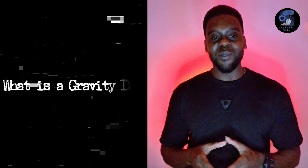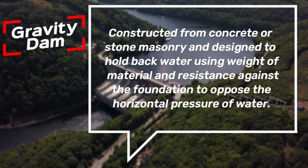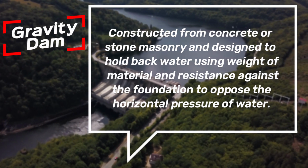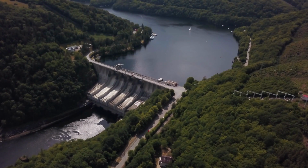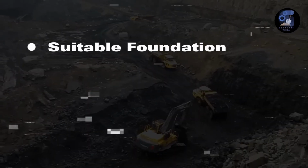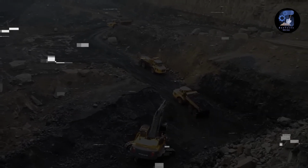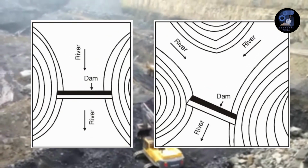So, what is a gravity dam? A gravity dam is a dam constructed from concrete or stone masonry and designed to hold back water by using only the weight of the material and its resistance against the foundation to oppose the horizontal pressure of water pushing against it. Of course, the ideal and most economical site location should have a suitable foundation for the dam, and the width of the river at the dam site should be minimum so as to keep the length of the dam minimum. In order to provide a large basin for the reservoir, the site should open out upstream.